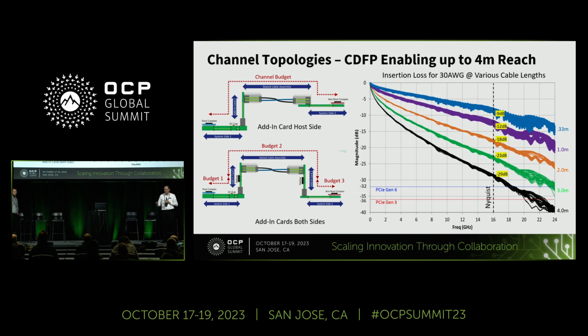So in the chart on the right, this is an insertion loss plot of 5 different cables. We're adding a 3 and a 4 meter cable to this. In this case, it's not de-embedded. So this is a little more similar to what you would have on that graphic, because the test board is not de-embedded, it's maybe similar to where you would have a retimer located relatively close to the interconnect.